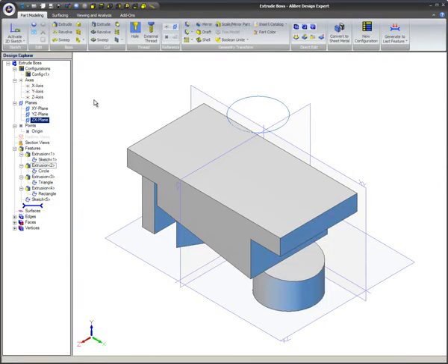When the part modeling features are used, the feature will be listed in the Design Explorer with that icon. So if an Extrude Boss is used, that icon will show next to the feature. If a helical cut feature is used, that icon will be shown in the Design Explorer. Once you learn what the icons are, you will be able to quickly see the features that created the part. If a feature fails, that part modeling icon will have a red X letting you know that the feature is in error.